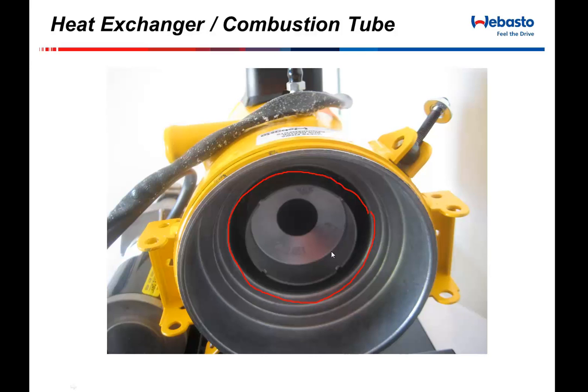That round disc that has the nozzle on it and has that photocell is making a seal on this cup on the inside. If that disc is bent at all, what will happen is that air that is generally going through this heat exchanger will actually turn around and come into that nozzle area, and you'll start putting a lot of carbon or a lot of black soot over the top of that photocell.